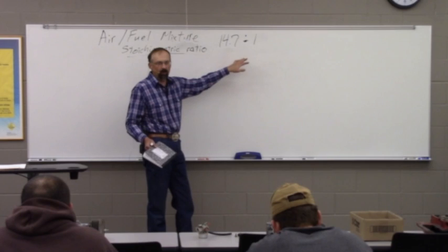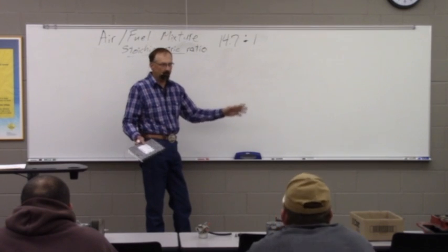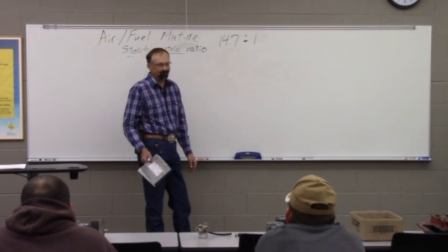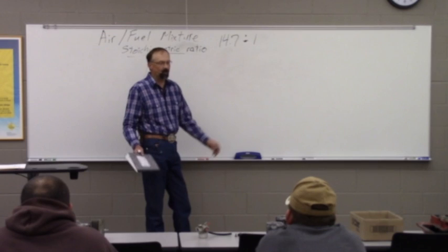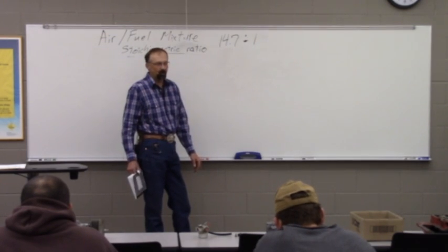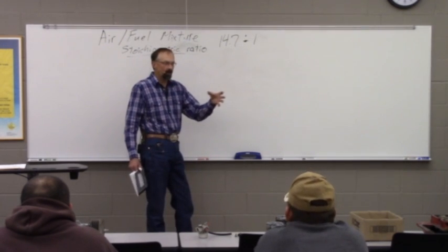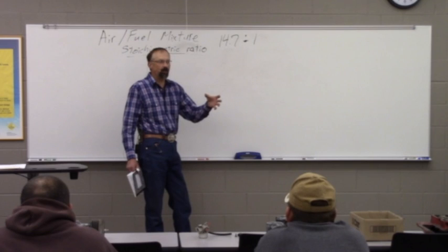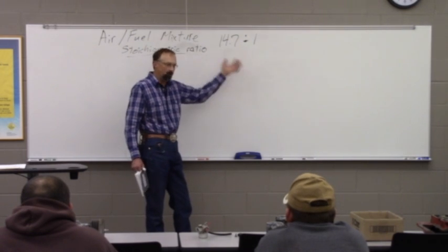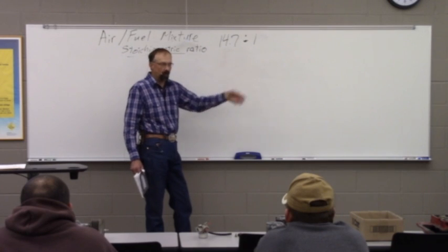If we've got a cold engine, we're trying to get started and running. When our temperature is down, you know, below 70 degrees, and especially if we're down below 30 degrees, boy, it's tough to get that flame to propagate through that mixture. And so we'll enrich it. We'll on purpose make it a little richer to get things started and running.